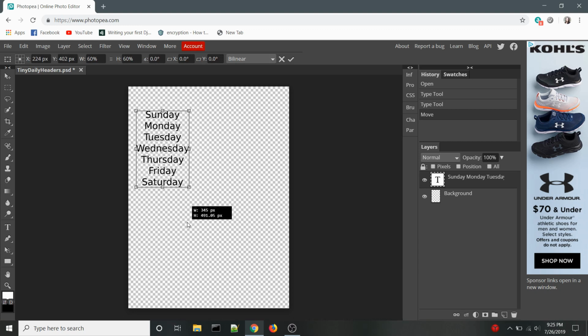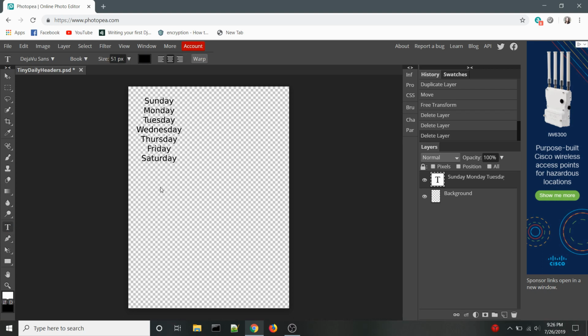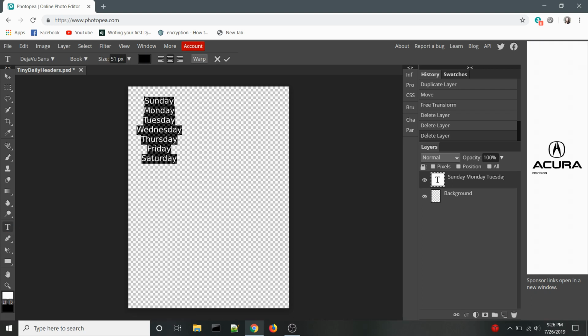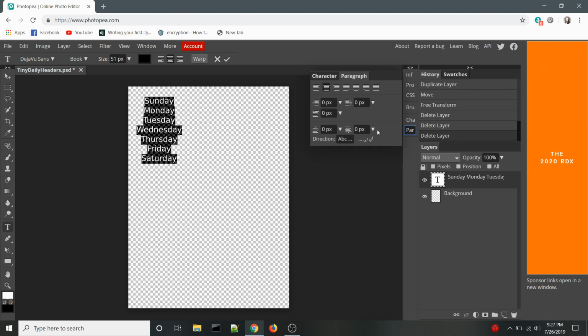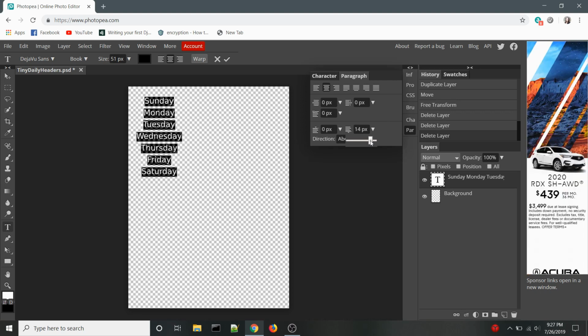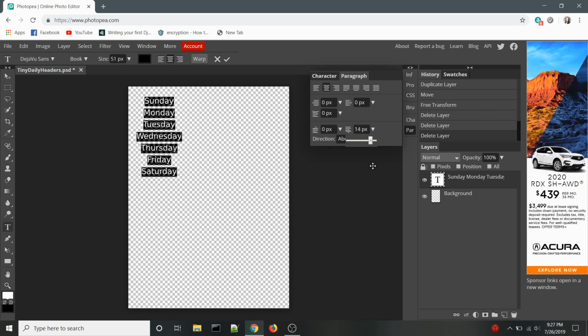Because these are going to be stickers, we need to account for some extra padding around each word so that the cutting machine has room to cut. It will take some practice to get an eye for how much space is needed. In the beginning, you will probably need to guess and check several times before getting it right. To add the extra padding we need between the words, click the Text tool, highlight the text, and then click the Paragraph button. Use the slider on the bottom right button to control the line spacing. Once the spacing looks appropriate, click the Confirm button and activate the Select tool.